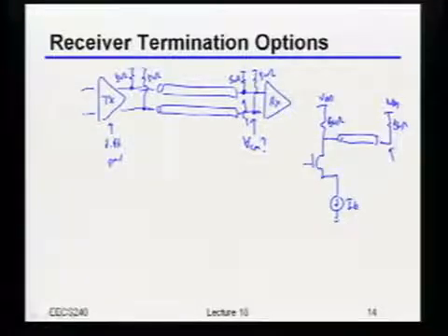Not really anything. No, it is set by something. I mean, I've got IB that's going to be flowing through 50 ohms. And of course, it's going to flow through a transmission line and flow through another 50 ohms over here. So what's the equivalent resistance looking up into that? 25 ohms, right? At least at DC.